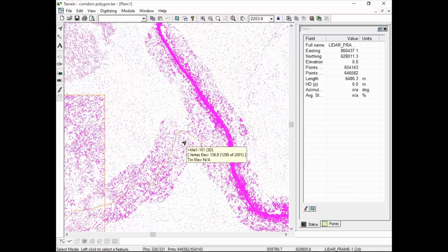It varies. If you've got a drone that's quite close to the ground, you'll get higher accuracy. Again, aircraft can fly slowly and close to the ground, or fast and high above the ground. You get different accuracies and so on. But ballpark around 15 centimeters. But where there's thick canopy, you're not going to get as dense a data set as where the ground is open. And that's about all I wanted to say about A, reading an LAS file, and B, thinning your data.